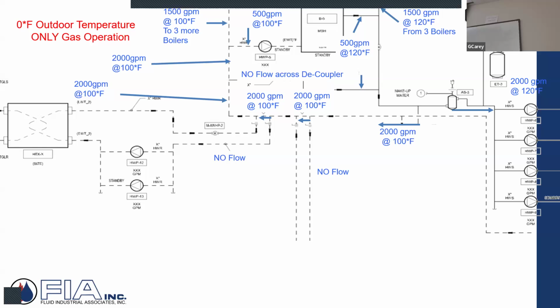It's just understanding that, like when you're dealing with large diameter pipe, like we were talking about here, it's not 12 inches. Could be 10 feet, but relative to, yeah, right. So that's okay. It's just that if the scenario, what he's trying to harp in the original design manual was, if you take those T's and you start to spread them apart, what happens to the pressure drop between the two? It starts to go up. Then you start to lose control. So really minimize that pressure drop.